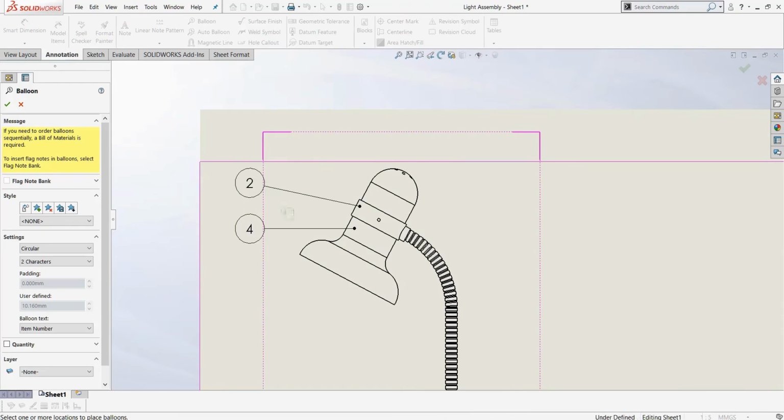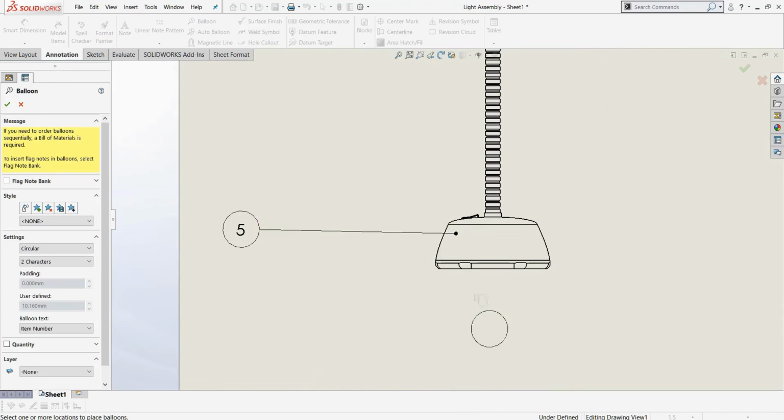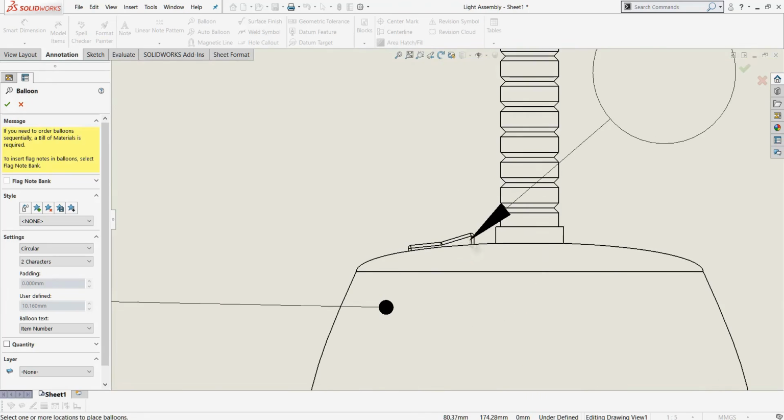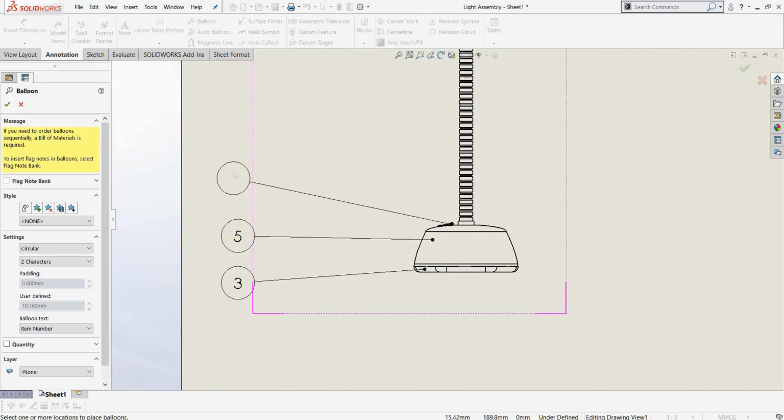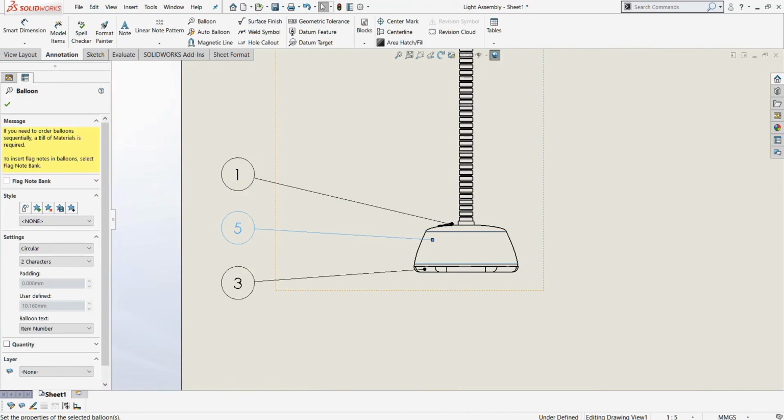In the second tab, I select the balloon to apply ballooning to these. Each piece is seen separately, and it automatically gives me different outputs because it knows these are another body. If I place this button better in line, it will look a bit nicer.